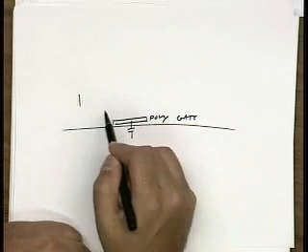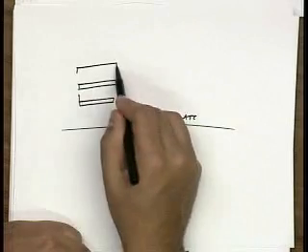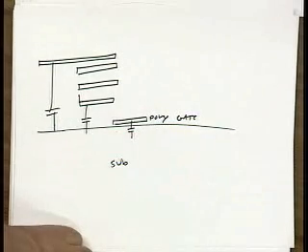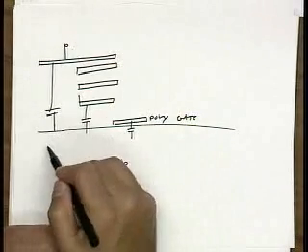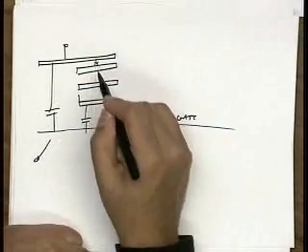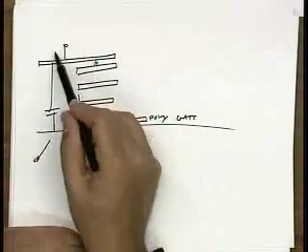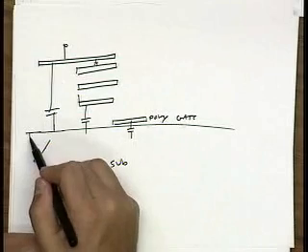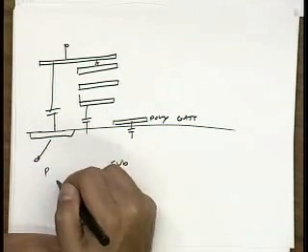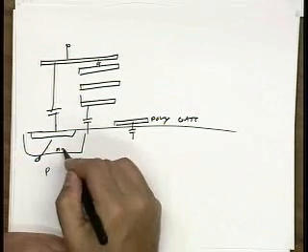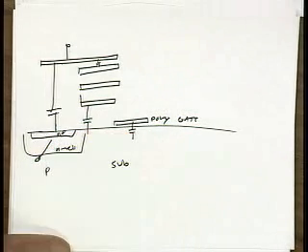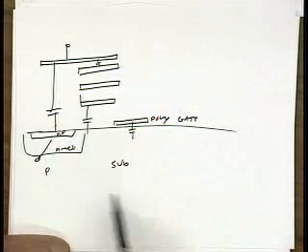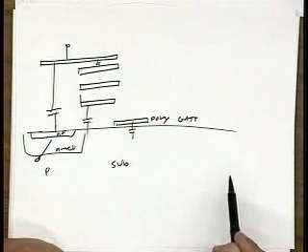And then you have basically metal layers, and they just do what they do. They're capacitors to substrate. So this is one plate, and this is another plate. So you have capacitances between layers that you can use, and you have capacitances from layers to substrate that you can use. Now, if you're going to use the substrate, you better put a plate there. So if this is P substrate, and let's say this is an N well for isolation, then I would put N plus here to form the other terminal of my capacitor. Otherwise, it's capacitance to ground, and a very lossy ground for that matter. Okay.